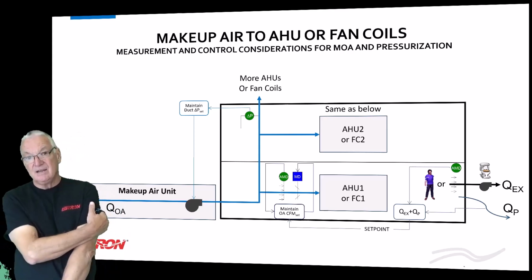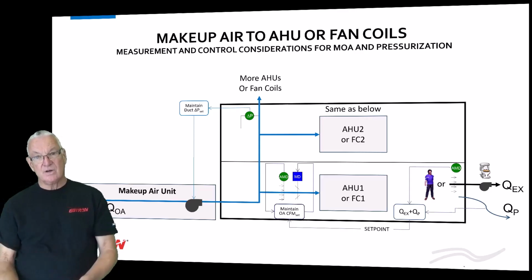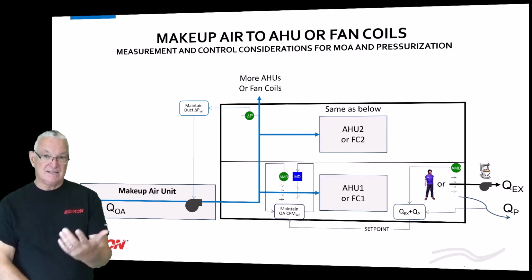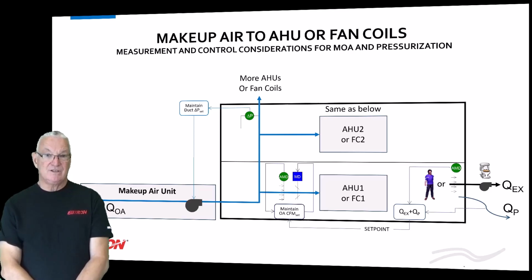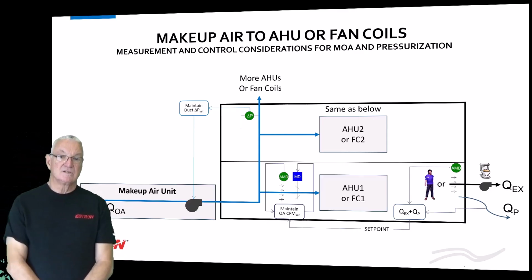At any rate, we want to measure and control that outside air to each one of those fan coils or air handlers. A lot of you use DP flow cross rings or whatever you want to call them. Listen, we make products for this that are much more stable. The fact is it's clean air. These units will last 15, 20 years, and not really require any maintenance or any calibration. You should really think about it. And it's not going to break the bank because they're application specific. Most of these ducts are relatively small, so we have products for that.